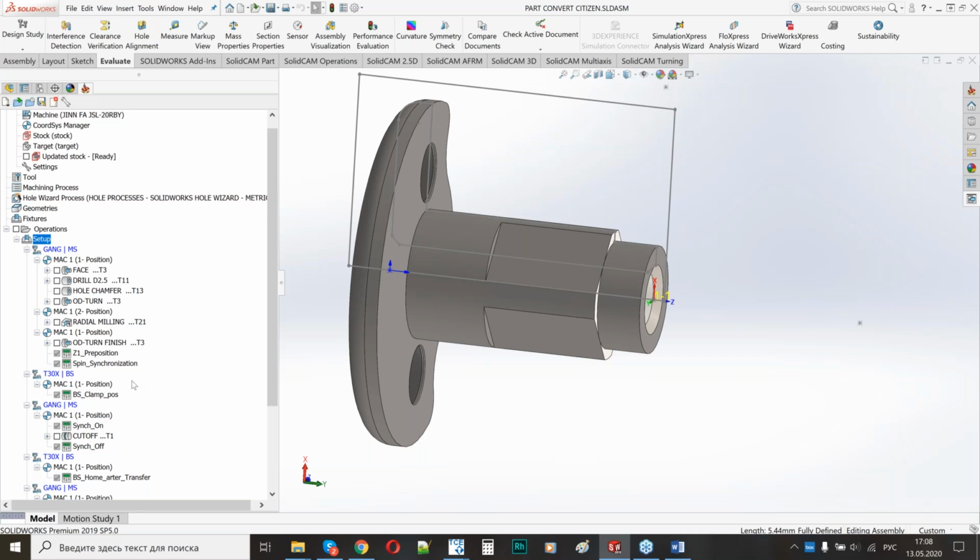It is very easy to program it inside SolidCAM, and as you saw, the long drilling operations and V-axis operation on the back spindle are not really complex in terms of programming, but you should understand what the machine needs, and SolidCAM can give the machine what it needs in terms of programming, in terms of adding wait codes, adding access patterns, whatever it needs, we have this inside the software.